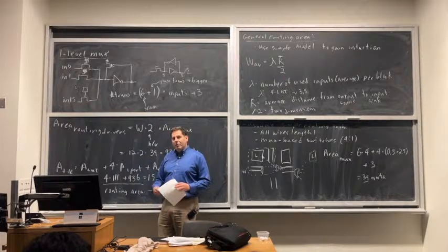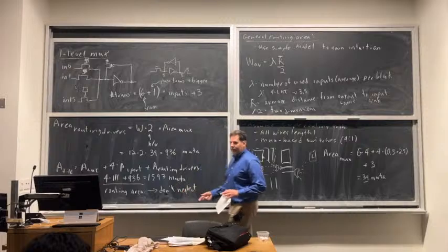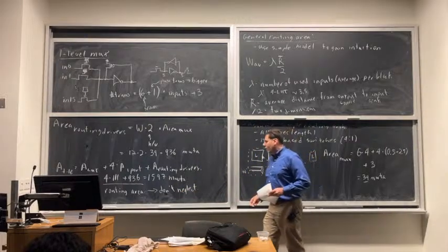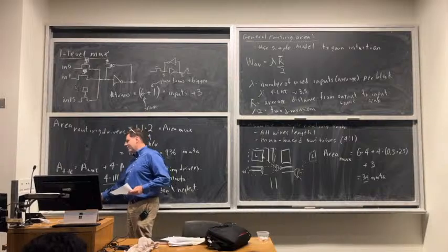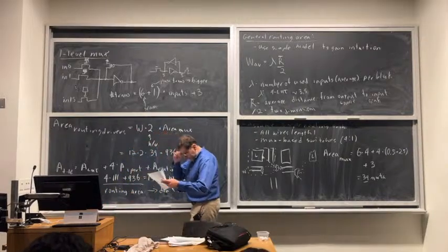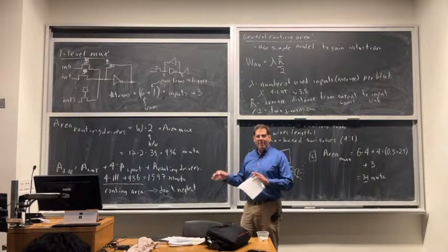Small lookup tables, short wires. You can optimize your routing architecture and your logic block architecture better than this. So you can, and people do, make FPGAs with less than 86% routing area, but you're still going to wind up at least 50%.